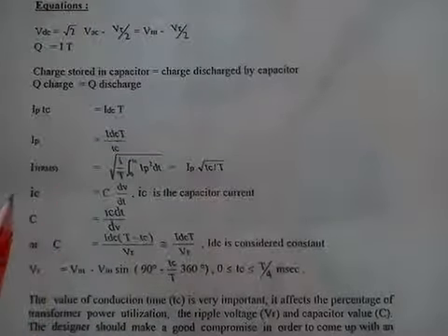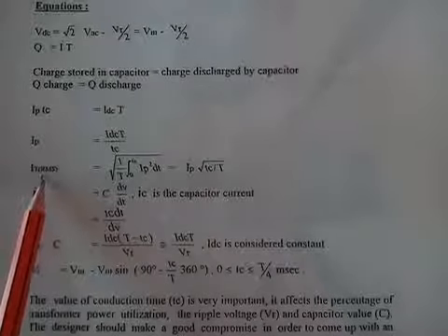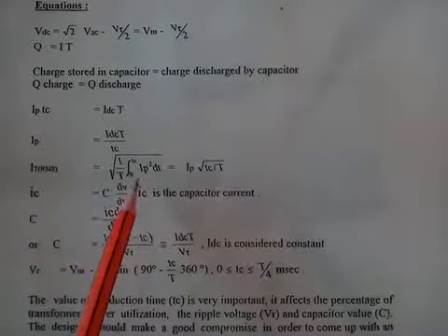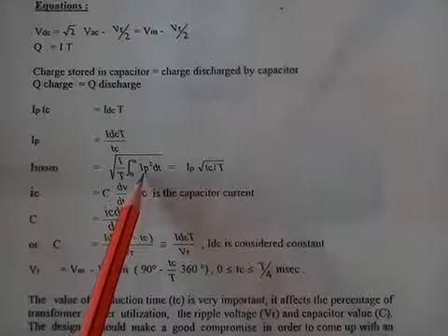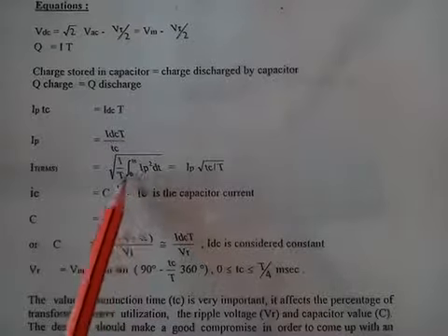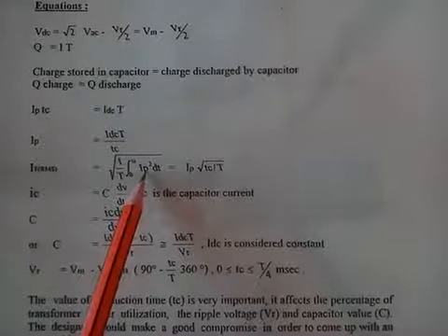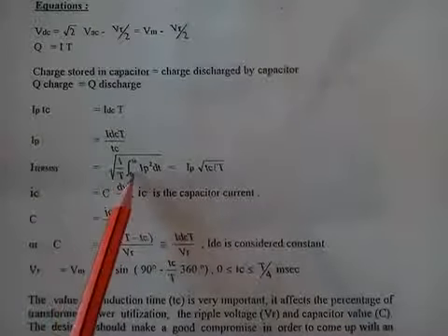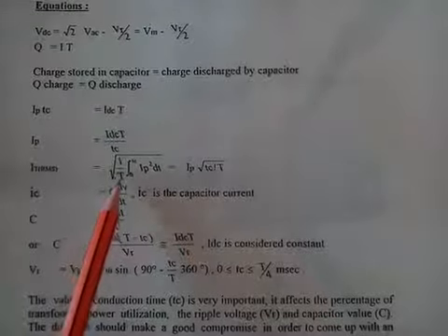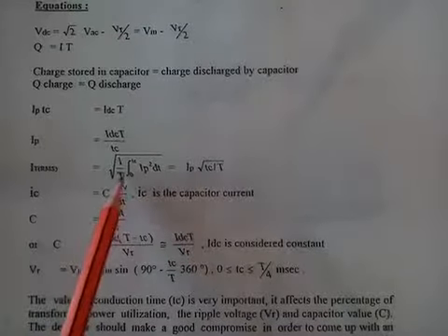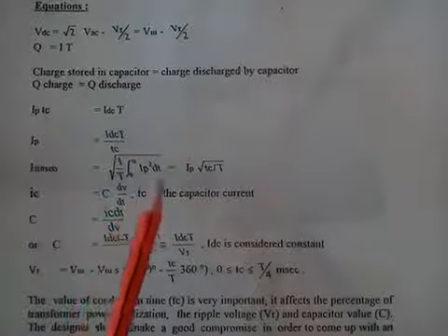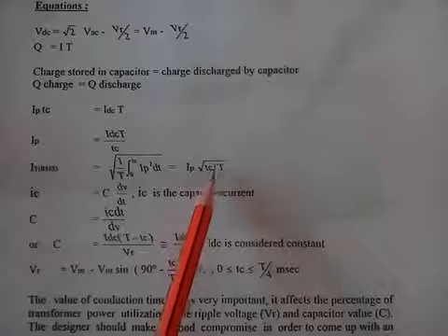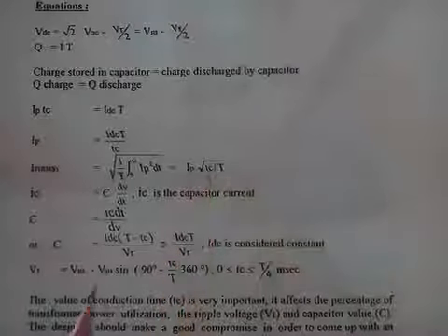And the RMS for such a waveform, that pulse that we had in there, would be found by squaring that peak current, finding the area underneath it, and after that averaging it and putting it under the square root. That's the RMS of any rectangular pulse that you have, which equals I peak times the square root of the conduction time divided by the whole time, the whole T.